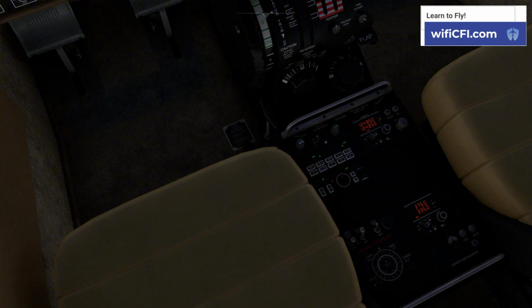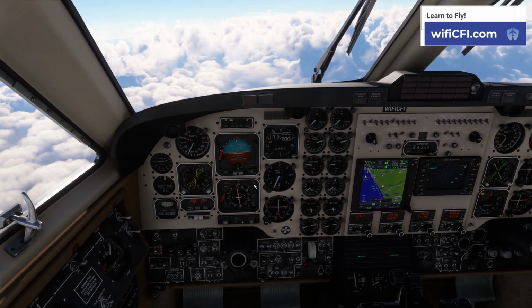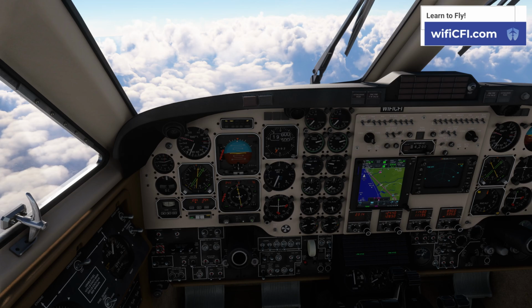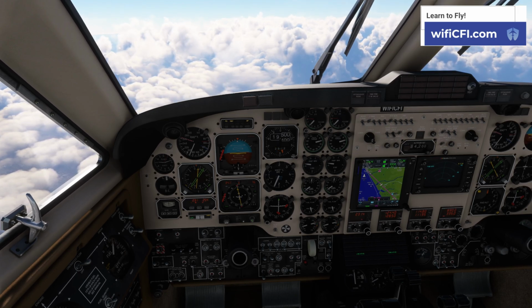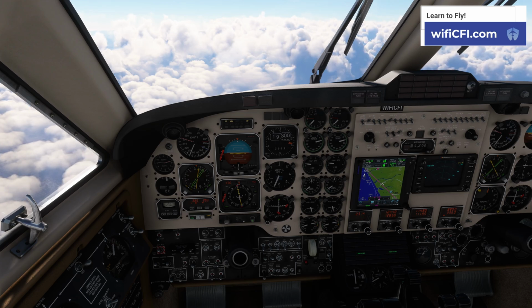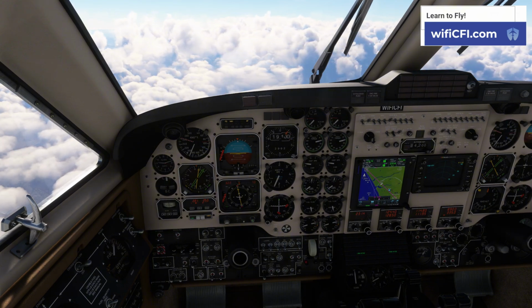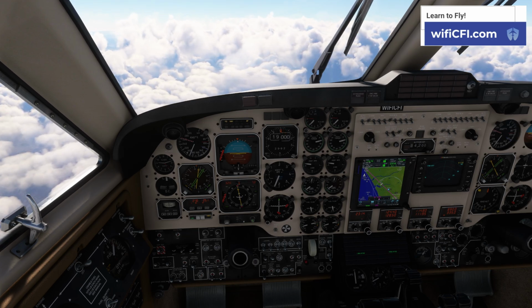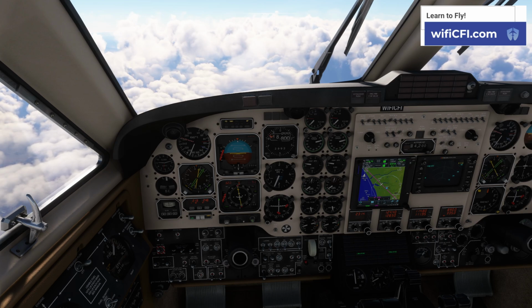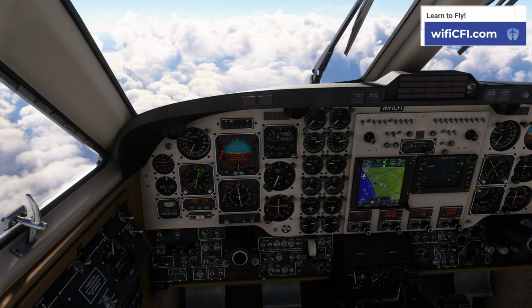Okay, pressurization is set. Arrival and approach have been briefed. Windshield heat, ATIS and AWOS we've got, and our altimeter will change as we cross that 18,000 feet. 4,200, everything's looking good. What was the altimeter setting again? I can never remember. 3009.